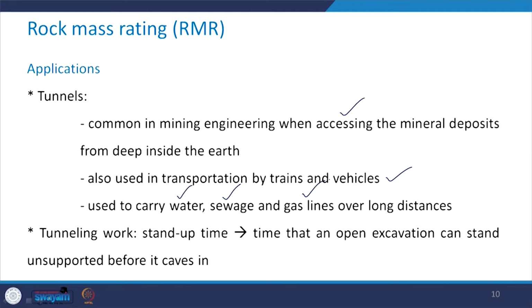As far as tunneling work is concerned, the stand up time is one of the most important aspects. How should we define this stand up time? It is the time that an open excavation can stand unsupported before it caves in.